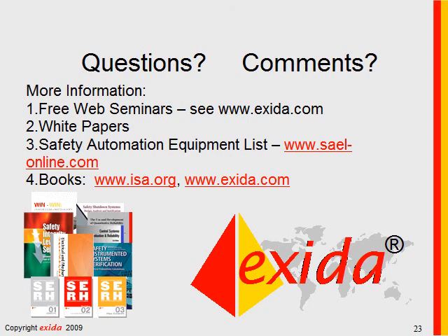I'll check one more. Thanks. If we use the same motor contactor for motor control and interlocking so that it is cycled, say once a day, would it be acceptable to use the following formula to calculate MTTFd? Well, the B10 divided by the number of operations, that looks like once a day, 360 days a year. I don't see any problem with that. Make sure you keep your units correct.